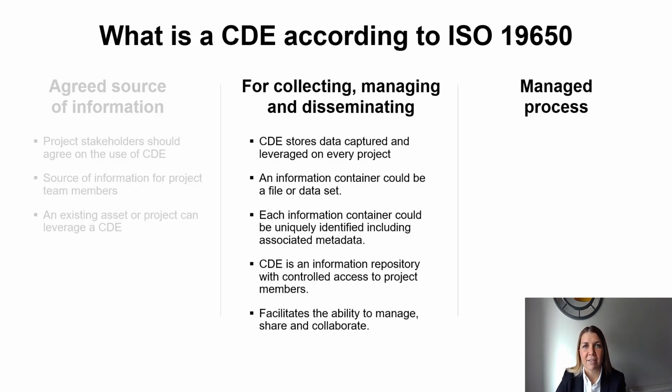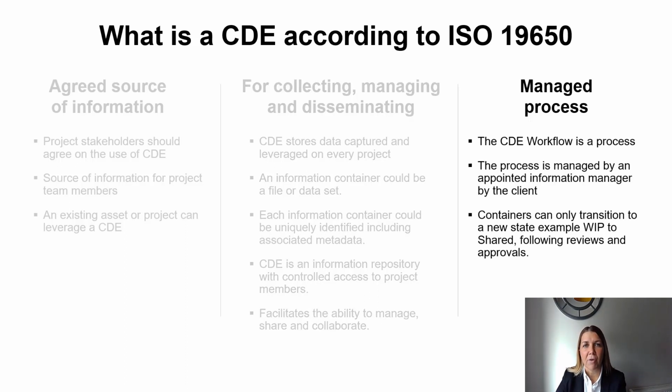Managed process. The common data environment workflow is a process, breaking down that process into 4 key states: WIP, shared, published, and archive. And to move that information container from one state to another requires an approval review to facilitate that transition through each state.